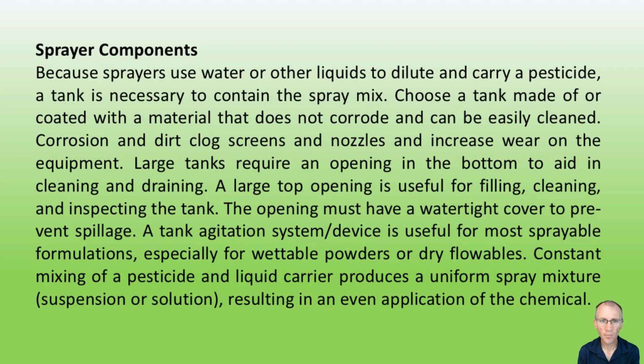We also need to look at the sprayer's components. Because sprayers use water or other liquids to dilute and carry a pesticide, a tank is necessary to contain the spray mix. Choose a tank made of or coated with a material that does not corrode and can be easily cleaned. Corrosion and dirt clog screens and nozzles and increase wear on the equipment. Large tanks require an opening in the bottom to aid in cleaning and draining. A large top opening is useful for filling, cleaning, and inspecting the tank. The opening must have a watertight cover to prevent spillage.